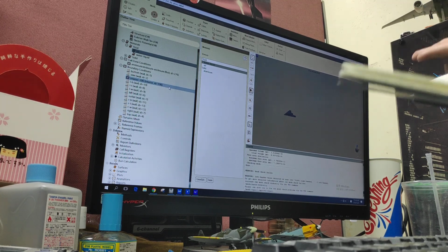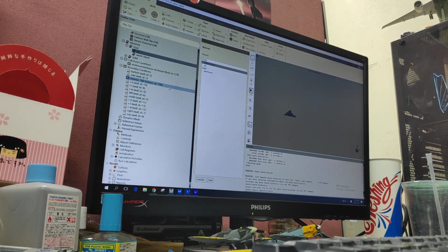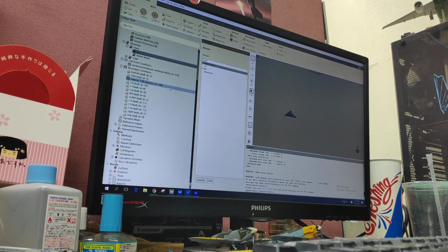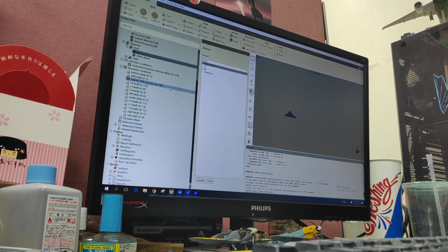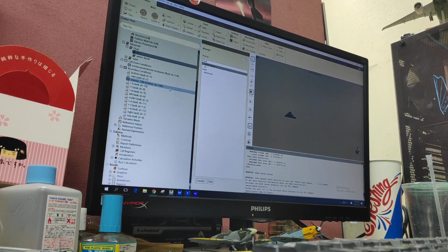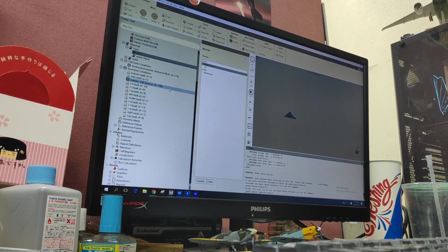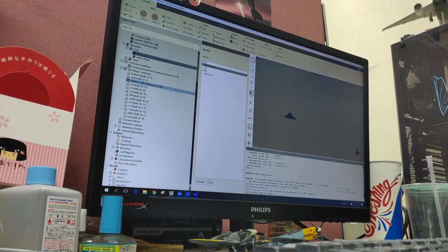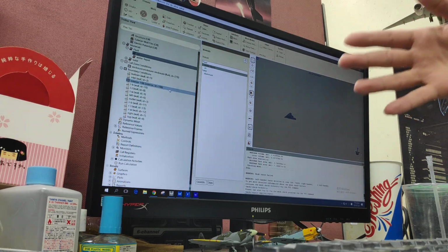But no, sorry. Pressure far field is only used in compressible flow. If we are in incompressible flow, we just use the wall, but we can change the number into this. This wall is a free slip wall.